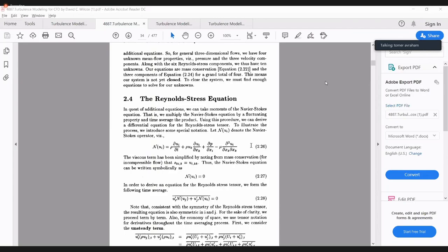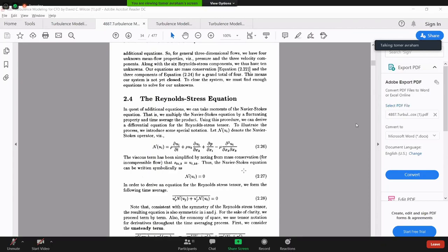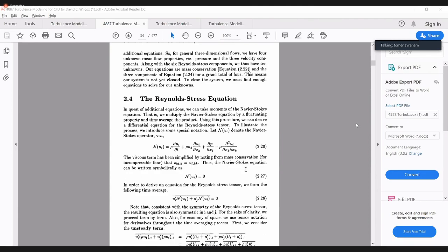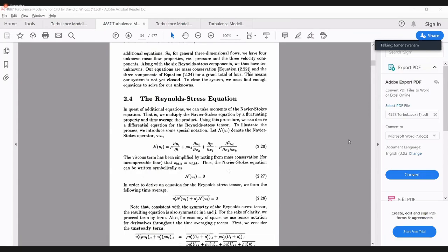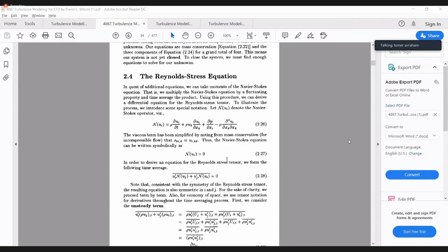To go even further than that, the closure problem, of course, we said two equations is considered to be closed. For incompressible flow, we have the continuity equation, which means that the divergence of the velocity vector is 0. We have three momentum equations. The pressure we get to constant, and then we have a constitutive relationship between the shear and the mean velocity, or what we call the symmetric part of the velocity gradient tensor.